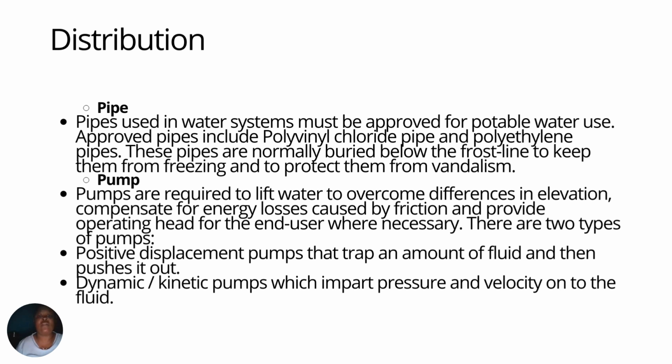Pumps are required to lift water to overcome the differences in elevation and compensate for energy losses caused by friction and to provide operating head for the end user where necessary. There are normally two types of pumps. Number one, the positive displacement pumps that trap an amount of fluid and then push it out. Then the dynamic kinetic pump, which imparts pressure and velocity onto the fluid.